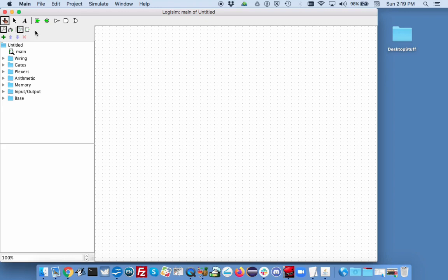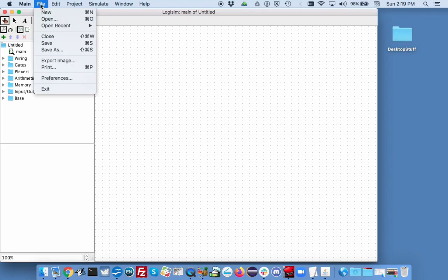In the menu bar, you will mostly use Save, Save As, and Open. Unfortunately, you cannot open a saved Logisim file by simply double-clicking on it in the file browser. You must open Logisim and use the Open menu pick. Furthermore, you need to have a current project open for any of the menu picks to work. So if you close the last project window in a session, you will need to quit Logisim and restart. Use Load to reload a circuit you were working on and saved.